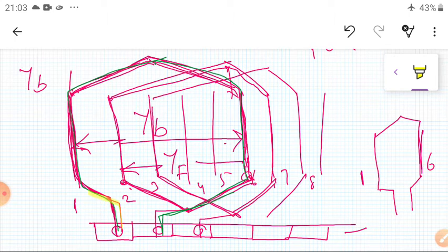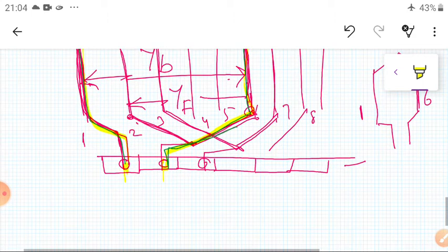So this is the one coil I have taken here. The distance between the two commutator segments: I connected one commutator segment here, and the same coil is connected here. The distance between the two commutator segments which contain the two ends of one coil. This is one end, this is the other one. The distance between these two is known as YC, the commutator pitch. This is the first coil and second coil, and this is the distance between the two. Okay, so these are the commutator pitch. Coming to the full pitch winding.